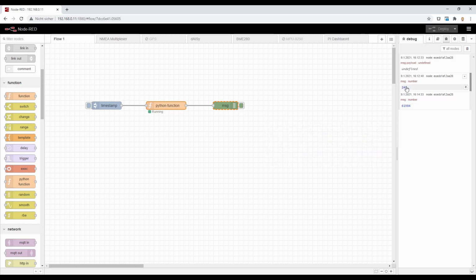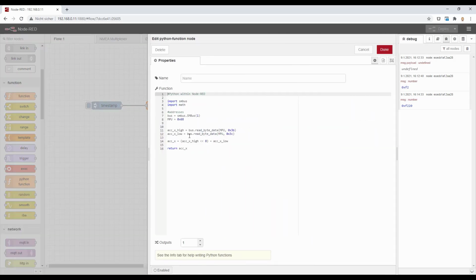It's decimal, it's base 10. But because hexadecimal is based on 16, this works very well. So we can see that this was now shifted to the high byte, and the low byte was 0, which we didn't see because we didn't hand this back up to now. So that's how we read registers and how we create one word out of it.